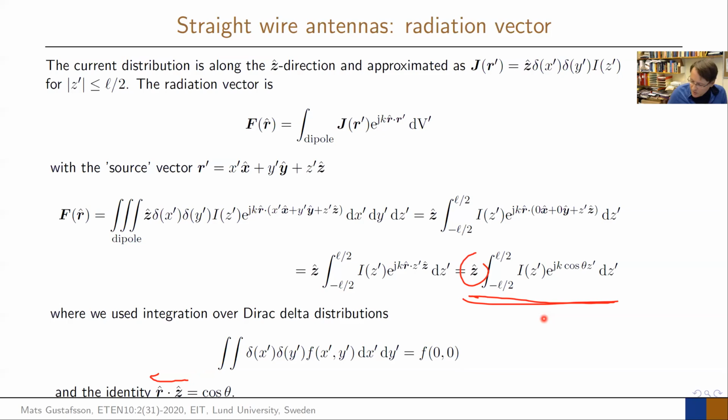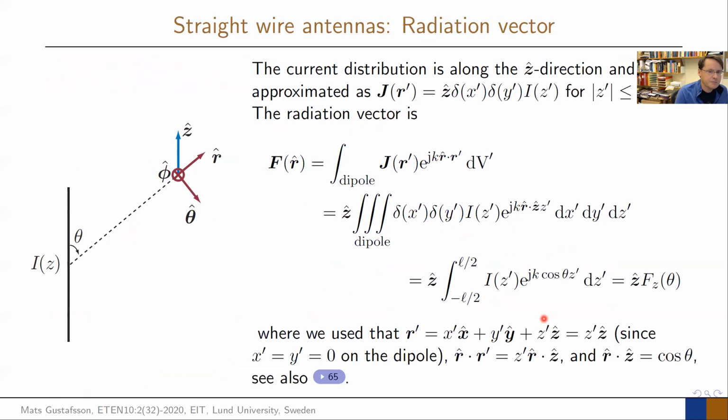And that's the part that sits here in these ones. That was this time delay: from the dipole, if I had the dipole here, sometimes I'm closer to the top and it's further away to the bottom. If I'm down here, it's closer to this point than this point. And that is what's compensated by this cosine theta and the z prime. And now I have to integrate that and sum it up, and I will know what my radiation vector is.